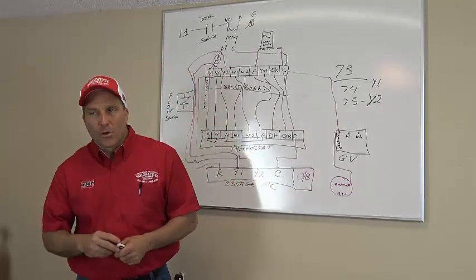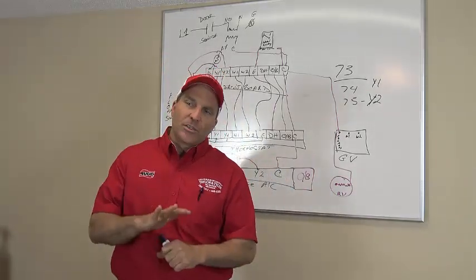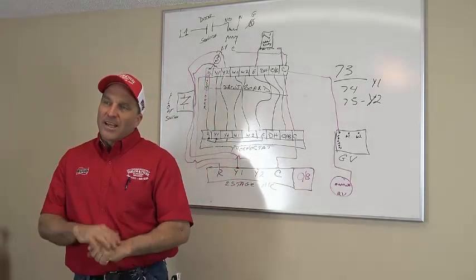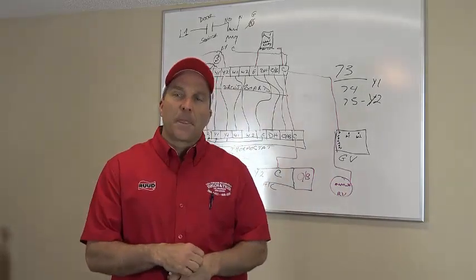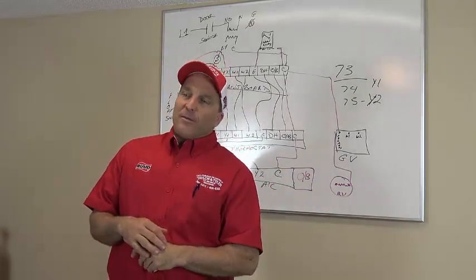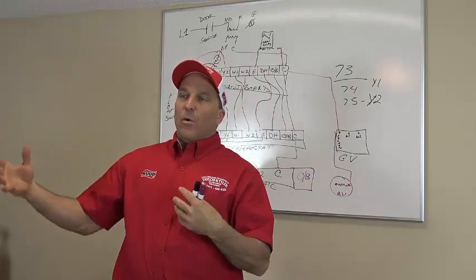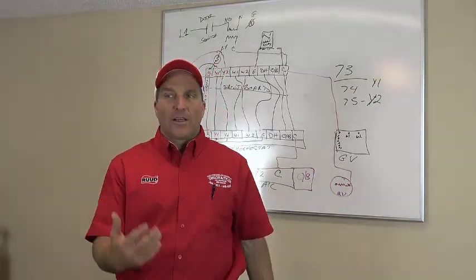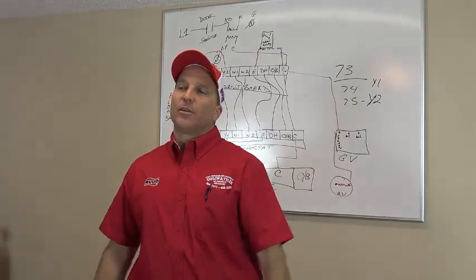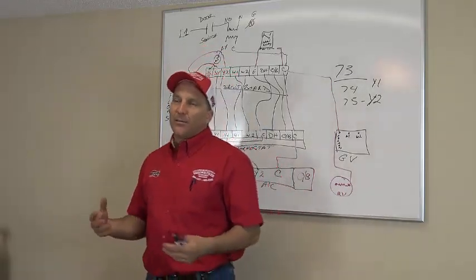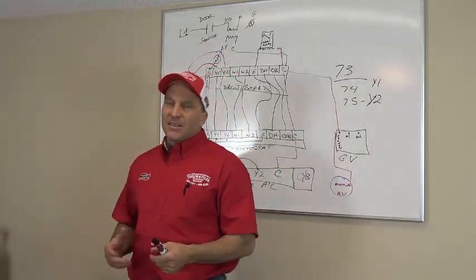Your pressures are different. You cannot charge a two-stage system when first stage is being energized only, because you have a 4-ton evaporator coil, a 4-ton compressor, but it's running at 2.5 tons. Your blower motor is running at 2.5 tons. You're not getting full speed on that system.